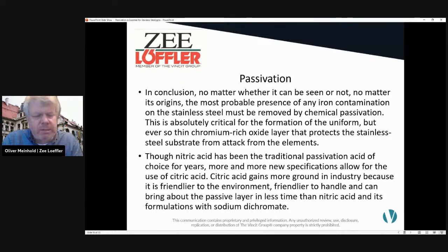Just make sure everything is properly labeled and tested for concentration, so that everybody passing by a tote or drum with this particular acid knows what's in there. And if you have a fully automated CIP system, which draws based on conductivity, of course it will draw a little bit more because we already have a dilution factor in there.